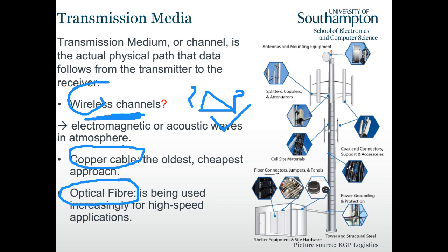So it's safer, the bandwidth is higher, and it's more green because the generation of optical signal should consume less electricity. We do not generate a carrier frequency and then use a mixer. What we do is stimulate electrons, and then light is generated.